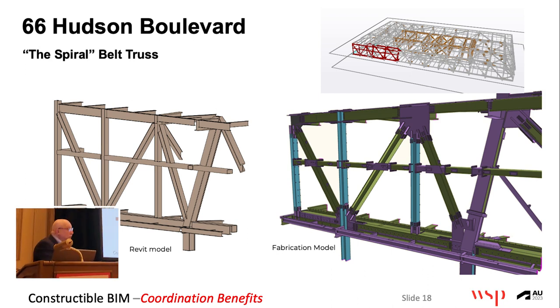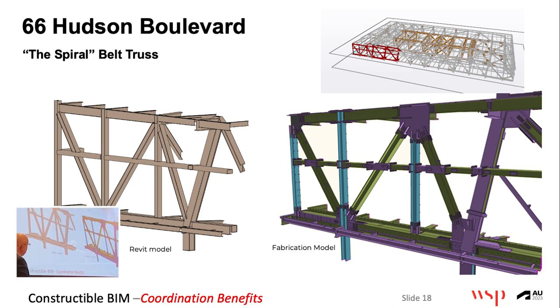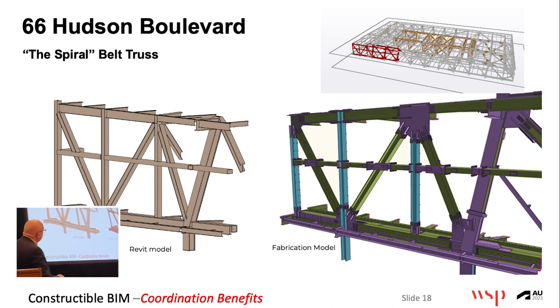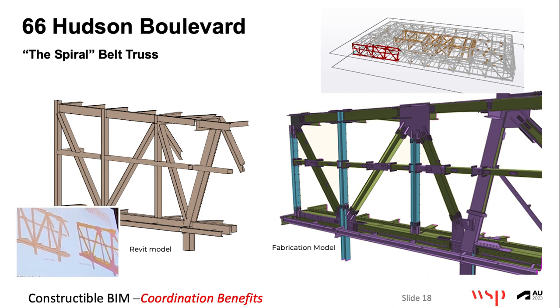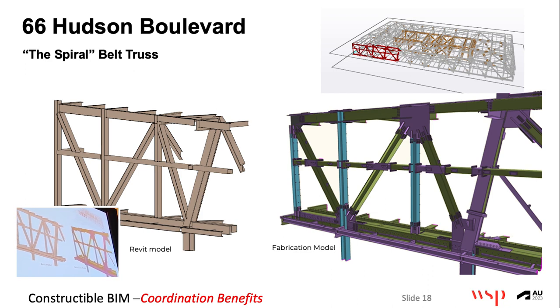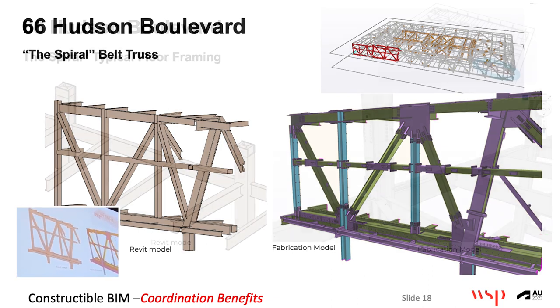You're trying to coordinate with the design team. By the way, trying to coordinate with the architects on the perimeter of the building, because this was a truss on the skin with the curtain wall and the attachments. And then constructability of how to make attachments for curtain wall. Curtain wall anchors, obviously, when you're next to gussets like this, it may very well be attached to some steel plate versus when you're far away, it's probably embedded in the slab. But this makes it so clear. And it helps the curtain wall bidders, it helps the erectors. It's a world of difference.